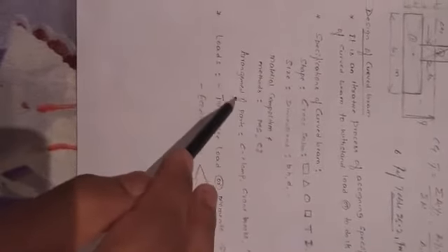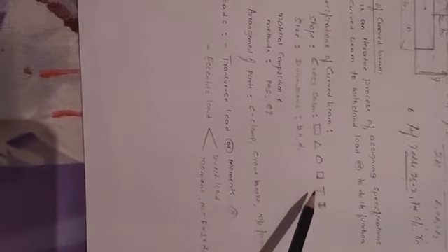Okay, then as you know, the design of curved beams, what is the design of a machine element? It is an iterative process of assigning specifications of curved beams to withstand load or to do its function. What is the specification of a curved beam? This is shape, size, material composition, and methods and arrangement of parts. What are the shapes of curved beams? It may be different machinery elements. You can use a C-clamp, crane hook, machine frame. What type of cross section is it? A rectangle, triangle, circular, square, T, I section, etc.